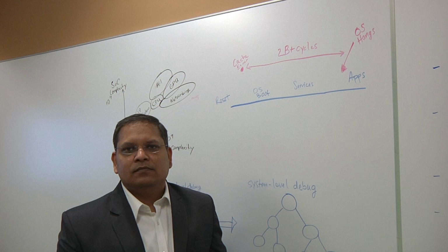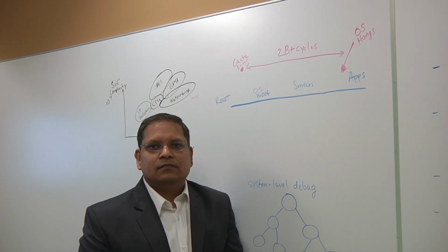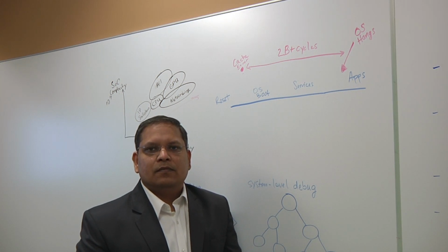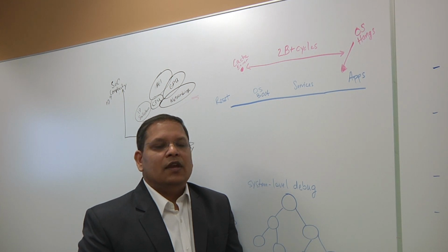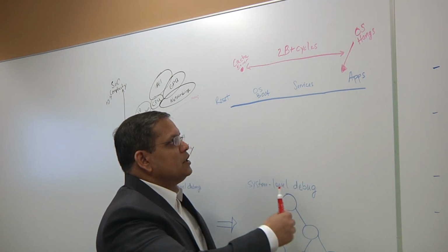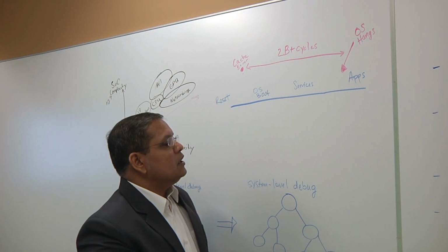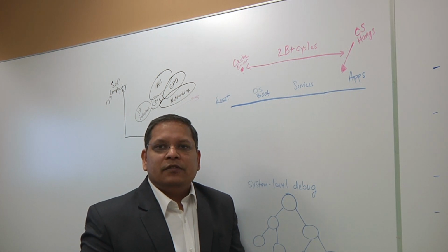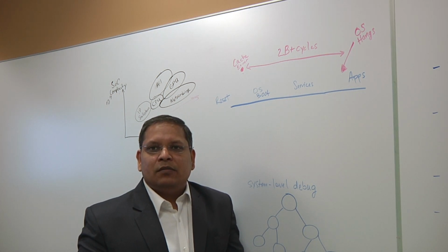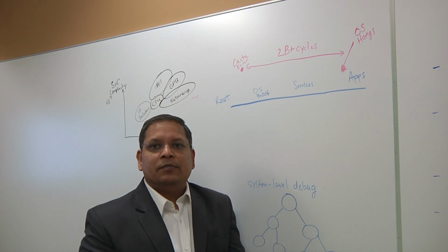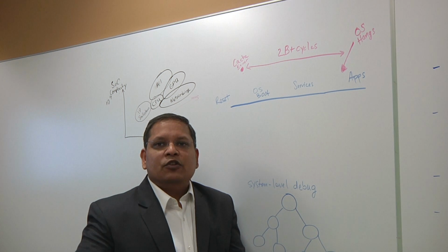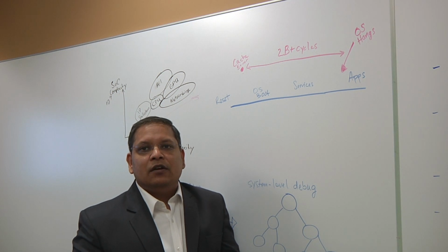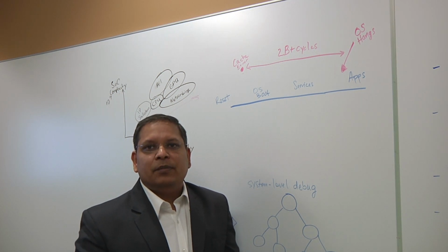Finding the root cause is no longer even just a single processor in a chip anymore, right? It's now, the root cause may involve software, it may involve multiple different types of cores, it may even involve multiple chips in a package. Correct. So this is where the challenge is becoming even more difficult, is that as you bring in more and more software contents, there is certain non-determinism that comes into the system because software is mimicking the real devices, and real devices by nature are asynchronous. So the timing of that is not determined. So we also need to bring in some sort of deterministic reproduction of the bug.